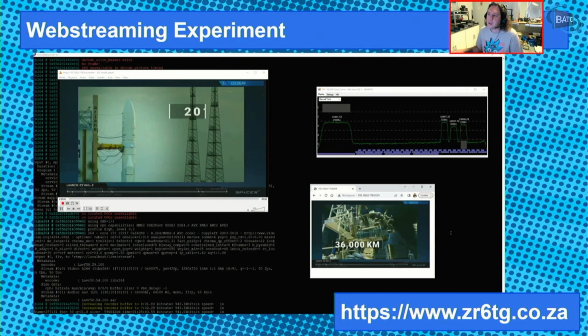The core concept is a web server with RTMP extensions. We use FFmpeg to take the video and audio from the Longmynd UDP port, and then we encode it with the Ryde codecs to stream it as an RTMP stream on our network or out on the internet. So we can essentially open a browser on any device and view the stream. So we are a lot less limited to specific devices.